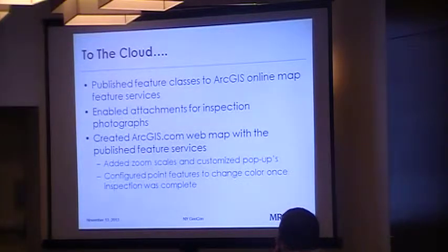I'm not going to go real in-depth into the actual process, but if you haven't used ESRI's ArcGIS Online, from desktop you have your data loaded in there. Under the file menu you can sign into your ArcGIS Online account and publish your data to the cloud. Very straightforward process. So we took our stormwater layer, published it to the cloud, and made it a private layer so it wasn't open to the public. It was protected from anyone going in there and doing anything to it.